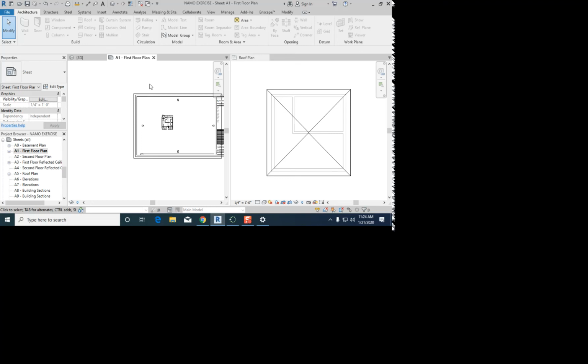Yep, so the dimensions or the constraints, right? So where's the constraints? Are we going to be drawing the center line of the wall? Are we going to be doing finish face exterior or interior? Okay, so we've got the constraints. What's another thing about the wall? So remember, we're not just doing plan view. Yep, the levels. Good. So let me just recap. The wall type or construction type, the levels, okay?